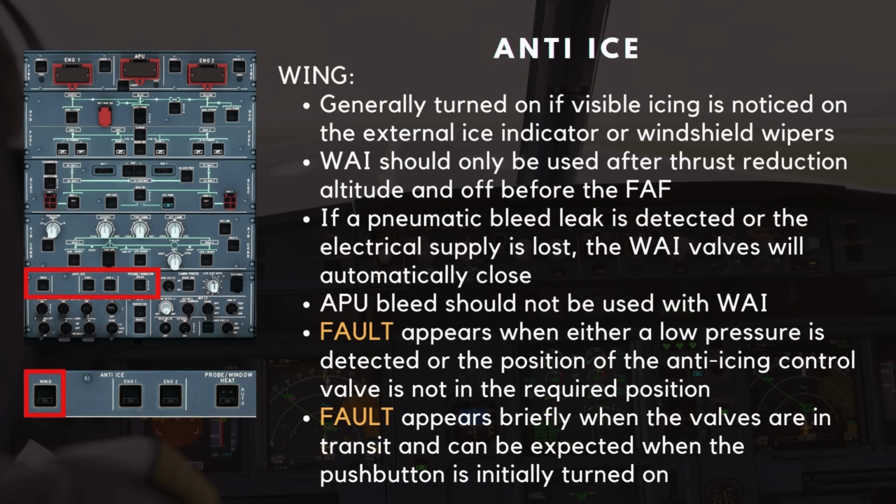This is accompanied by an ECAM caution. Note, the amber fault light does appear briefly when the valves are in transit, so this can be expected when the push button is initially turned on.